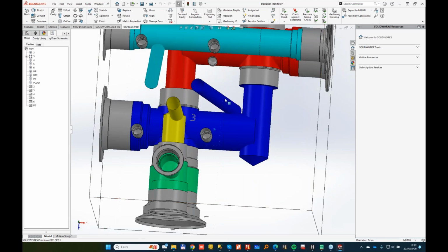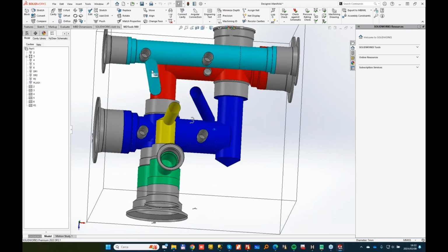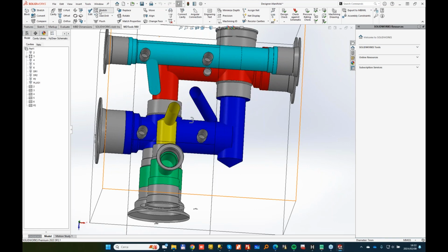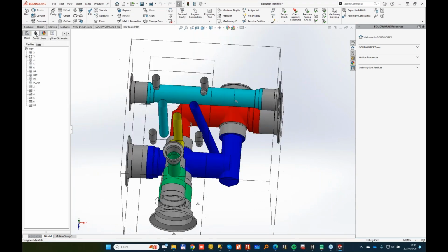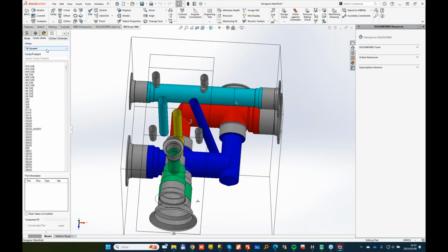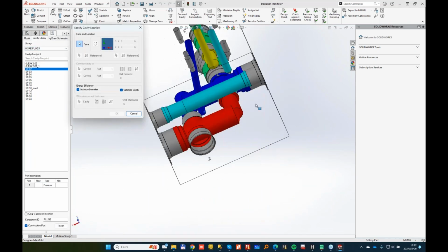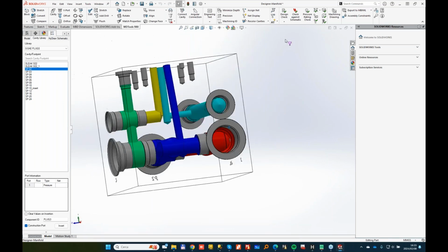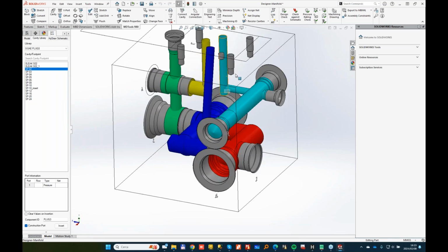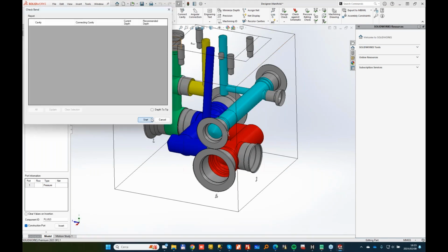Since I have an inclination in this direction, it is not convenient to have this drill in the other direction as well. So I will make it straight. So no inclination here. And I'll add a construction plug. So I go to my cavity library, go to my short port plugs and take a short port number 2 and place it on this side, connecting here and here. Eventually, I can optimize a bit the drill depth. So by using the check band command, I will be able to optimize the drill depth.